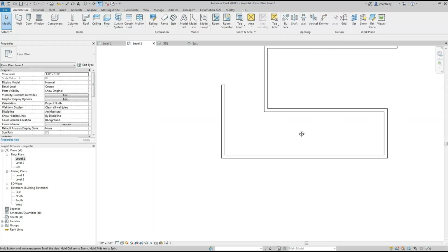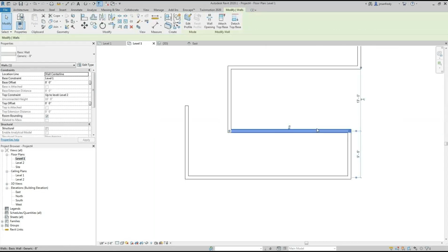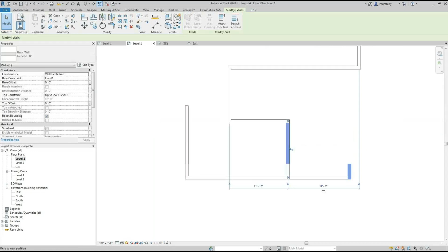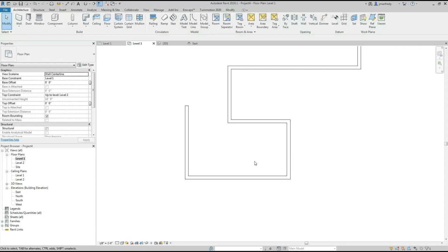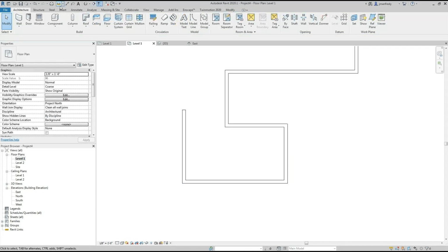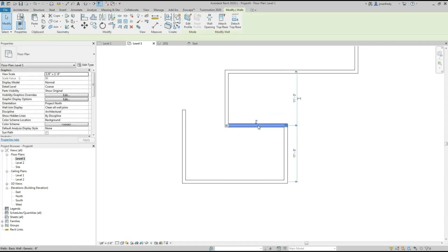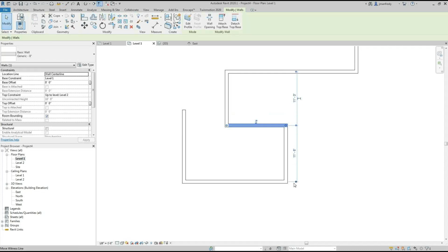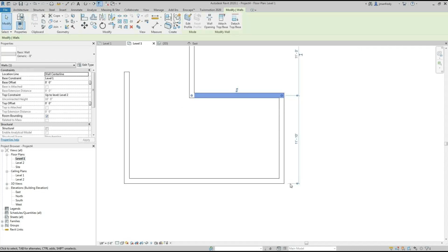It flexes the model and moves things around. So you can use this to arbitrarily drag things around, right? Or you can simply type numbers in here if these are important to you. If you want to take a measurement, you can use a tape measure here and just go from corner to corner and it tells you how far away that is. Or this corner to this corner and it tells you how far away that is. But sometimes Revit has good guesses. It makes good guesses here. You might just have to move these little object lines, these witness lines, by flexing that little dot right there.